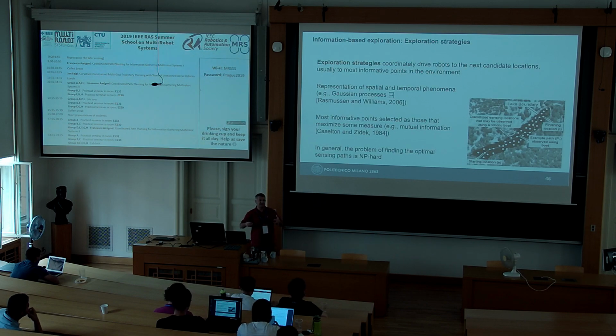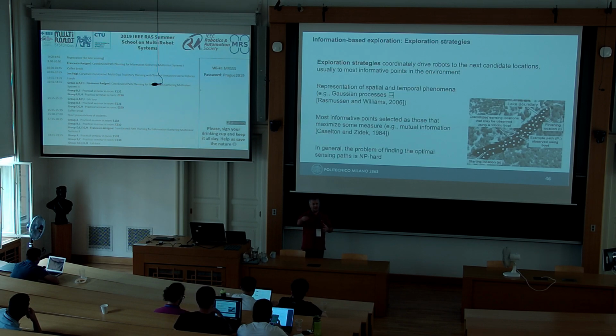And so the representation of what you know is basically a map of the environment. Let's say a typical representation is a grid map in which you have known cells that can be free cells or obstacle cells, and you have unknown cells that you have not yet sensed. Okay? So in the case of frontier-based exploration, it is easy to represent what you know about the environment.